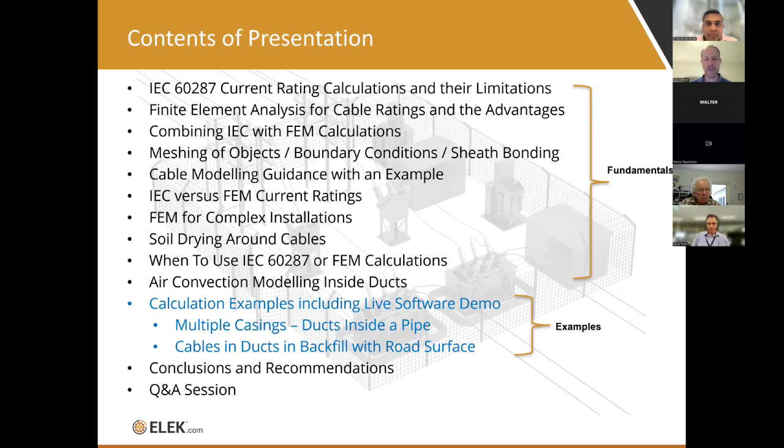When to use IEC or FEM, air convection modeling inside the ducts, and there'll be a couple of calculation examples. So it looks like multiple casings, horizontal directional drilling, you've got to use FEM. Cables in ducts in backfill with a road surface, you've got to use FEM because you've got multiple zones of different soil thermal resistivity. I'll draw some conclusions and recommendations, and then we'll have a Q&A session.